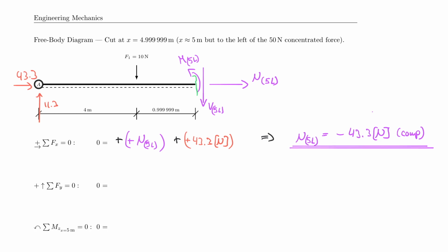And I can move on to the next shear force. So the shear force here, I start with that unknown. Again, it's always positive, V of 5 to the left. And yeah, I understand that it's not really positive according to what you think, because it's pointing down, but I do that with my black identifiers here. In the parentheses, I always remind myself that an arrow is always positive. So now I have to identify that it's actually negative going downwards.